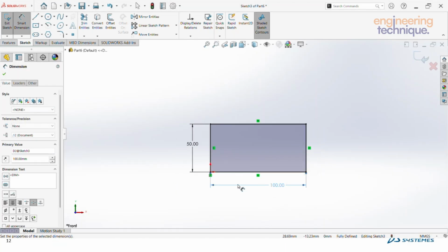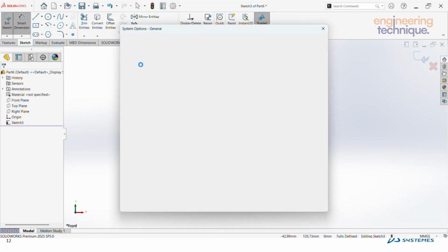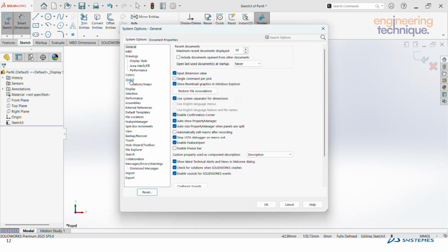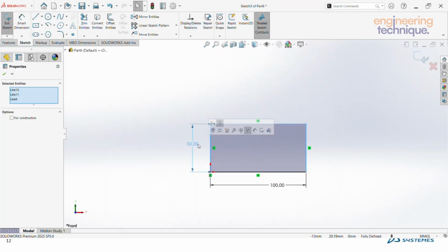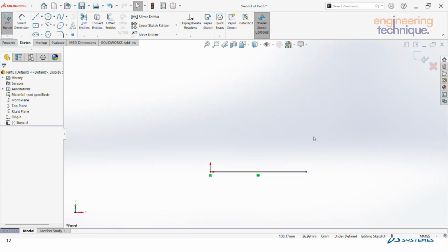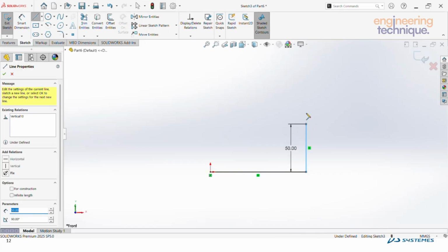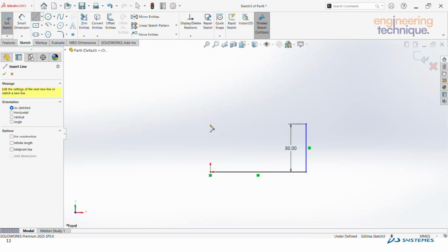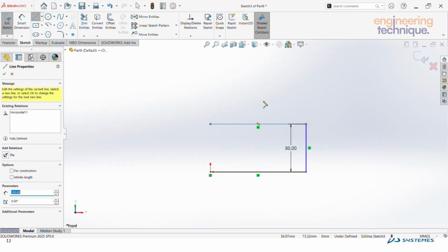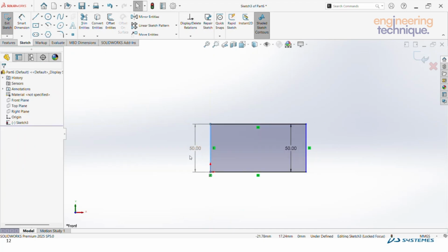As we can see, we directly input it and created that reference here with the same option. If I unselect this and this also, in that way we can directly create particular geometries. For example, by selecting that option, it automatically gives the particular dimension to that line. Here I can write 50, and it automatically inputs that dimension.